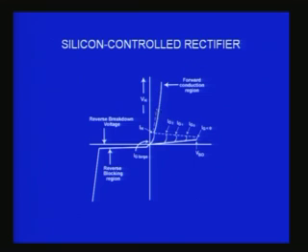That shows that it is in the conduction region; it is conducting now, the SCR. Now if I apply a gate current Ig0, Ig1, Ig2, etc., then depending upon the magnitude of the gate current, I can switch this on much below the breakover voltage, or still below, depending upon the magnitude of the current. These are different points at which it will break over, and then it will come over here.